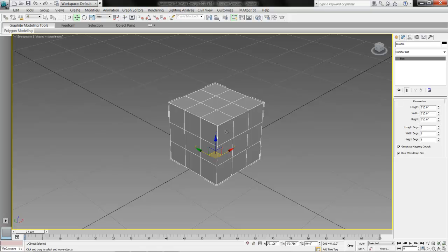The reason you would want additional segments is if you're trying to modify this object. Depending on what modifier you want to add to it, you would need additional segments or more faces. Once it's divided, you can choose one of the cubes and extrude it, enlarge it, distort it, but it still belongs to the larger cube.